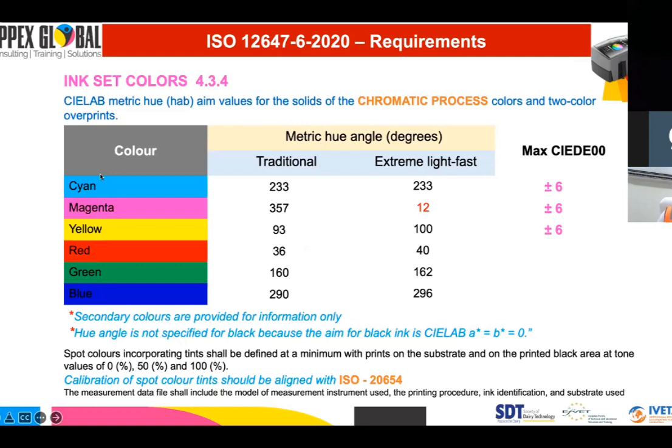And so we need to consider how it gets from there to the final edge, but all we talk about in the standard is the angle or the color of the ink. And you have that conversation with your ink provider. And so if they're providing you inks that are to the standard, they have to measure at this angle, but how dense you make them, how far they go out is based on the viscosity of the ink. So the final density is metered, and that is via the density and the viscosity.